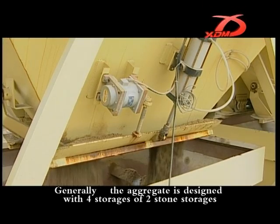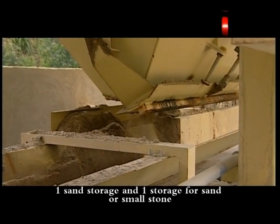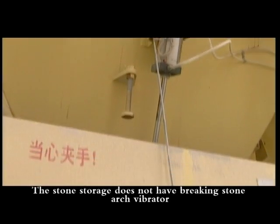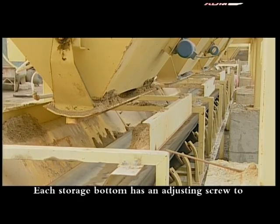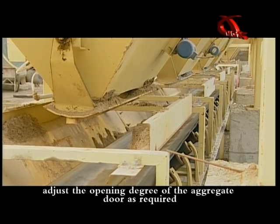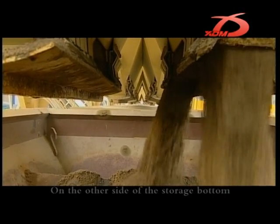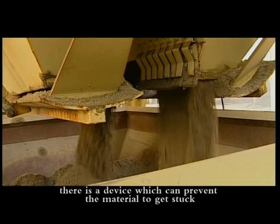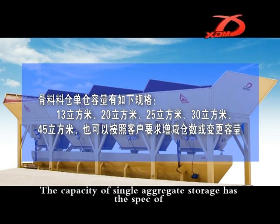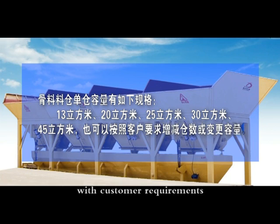Generally, the aggregate is designed with a total of 4 storage deposits, 2 for stone, 1 for sand, and 1 for sand or fine stone. The stone deposits do not have a vibrating arch to break the rocks. The bottom of each storage deposit has a screw to adjust the opening degree of the aggregate door as required, controlling the flow of the materials. On the opposite side of the storage room, there is a device to prevent the material from getting stuck. The storage capacities of a single aggregate are 13, 20, 25, 30, and 45 cubic meters, which can be changed according to the customer's requirements.